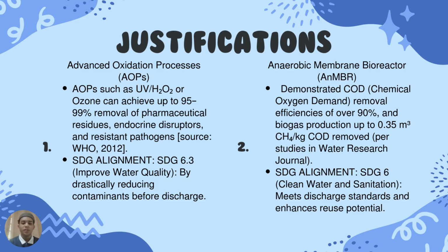So for the justifications for these two solutions, for advanced oxidation processes, AOP such as UV/H2O2 or ozone can achieve up to 95 to 99% removal of pharmaceutical residues, endocrine disruptors, and resistant pathogens. As for the SDG alignment, it's SDG 6.3, improve water quality by drastically reducing contaminants before discharge.